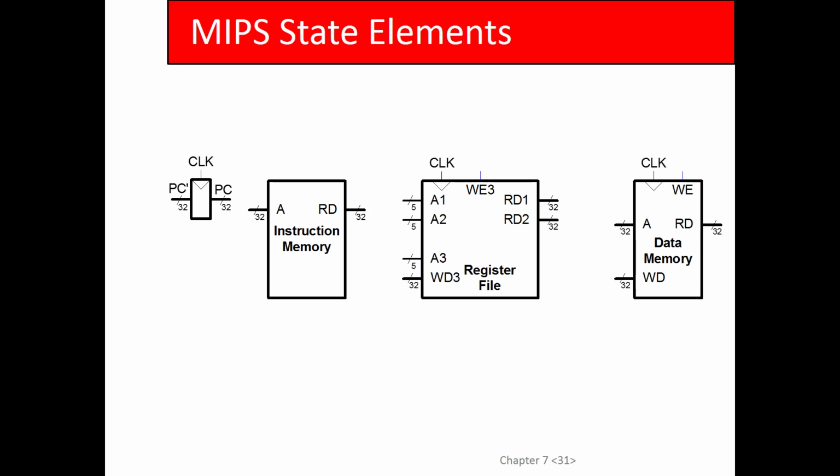Instructions are in here, so we're basically taking an instruction address and it spits out the instruction at that address, right? So our program gets loaded into this guy. Now you might say, well, is that on chip or off chip? Where is that memory? It's generally going to be on chip. There's going to be a cache, and then if you need more than fits in the cache, it would be backed up by a larger off-chip memory.